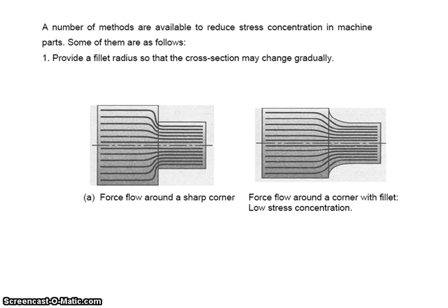Now when the fluid is flowing through a pipe and a sudden reduction in the area of the pipe happens, in order to maintain the constant flow, the streamlines get narrowed and become very close to each other, and there is a sharp bend of the streamlines at the corners.